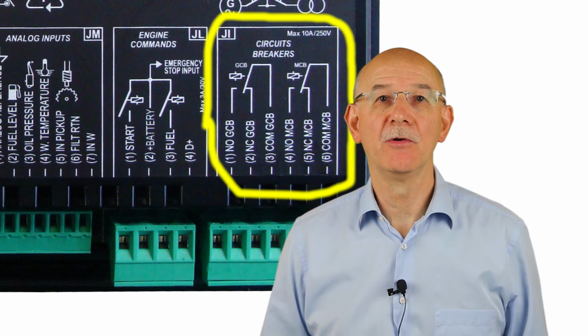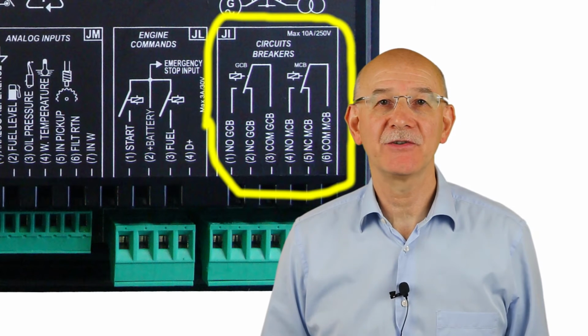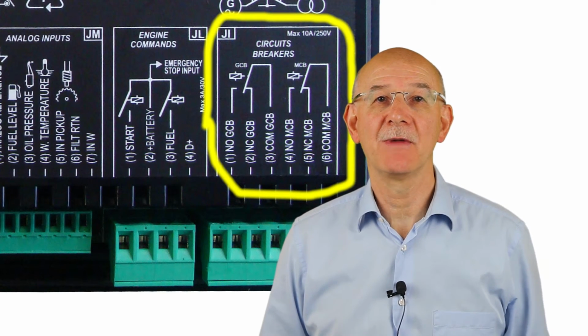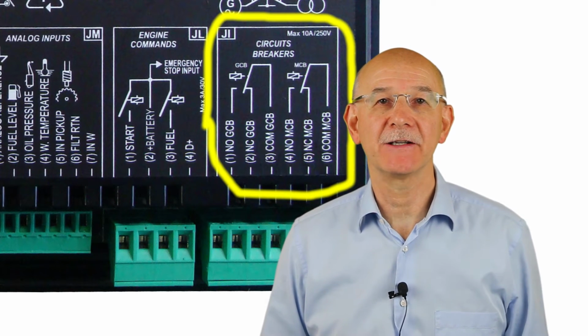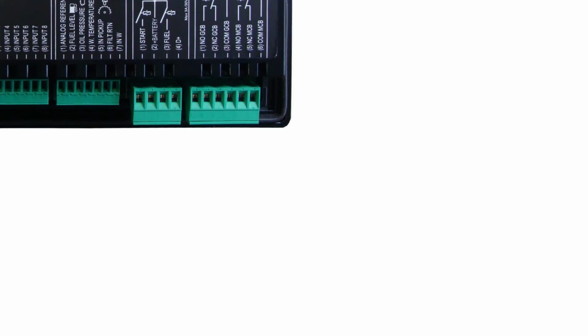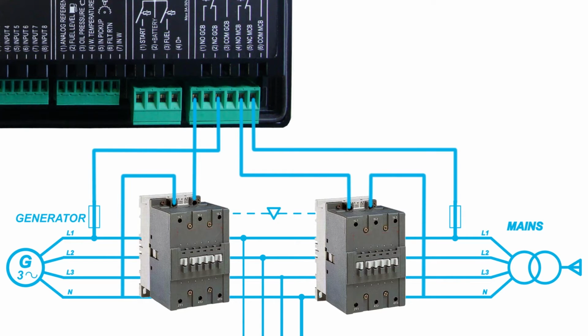A digital output configured for stable mains circuit breaker command using function 2004 is activated in order to open the MCB. Thus, the normally closed contact of the relay should be used in order to command the breaker. The advantage is that in case of controller power off, the MCB is automatically closed. In any case, you can reverse the operation by the checkbox to reverse the functionality.